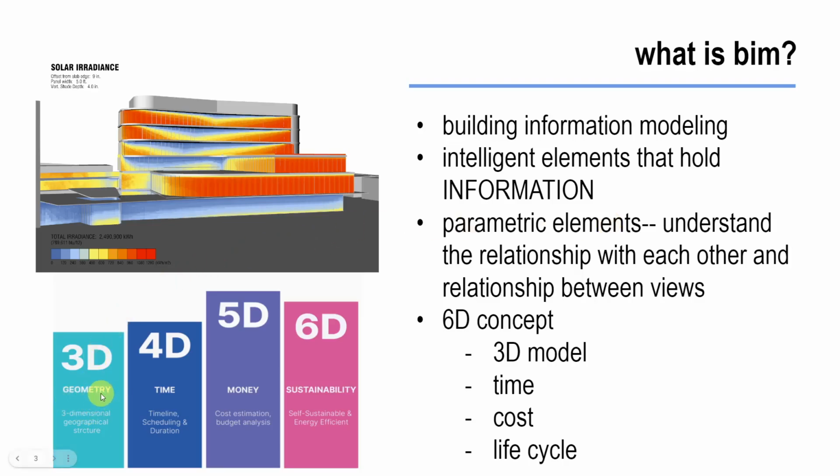But not only are we creating just 3D geometry of our form and our shape within our building, within all of those parametric elements, we can also put in a schedule for when parts are going into the building or when demolition might be happening, when pieces are arriving for it. So we can schedule things out as a project manager within BIM. We can also, within each of those elements, if we know what our wall is made out of, figure out how much drywall we need to purchase, because we know exactly how our wall is getting framed out within our model.